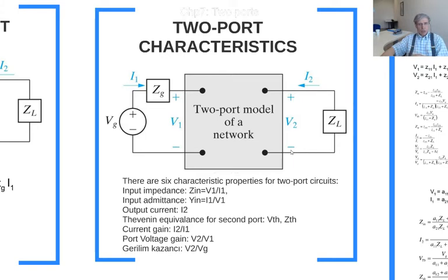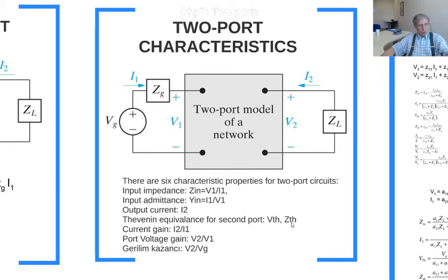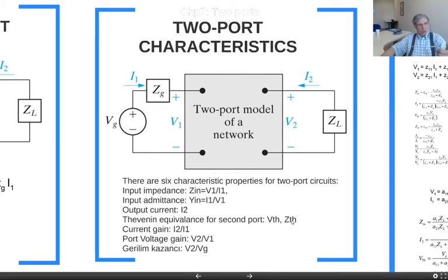Otherwise, you're going to lose some power in between, isn't it? Because if the Thevenin equivalent impedance is high, in the Thevenin equivalent circuit you're going to consume some energy, power. If you don't consume that energy and power, that means you transfer that power to your load. So this impedance seen from this second port must be as small as possible.